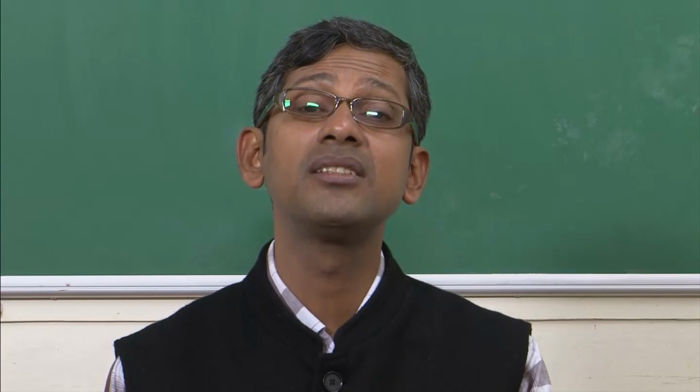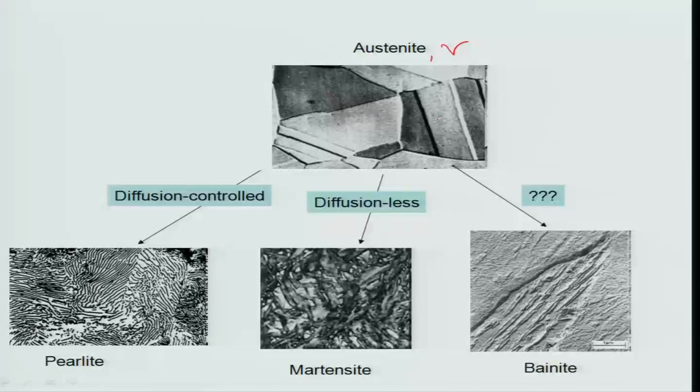Martensite is a single phase structure, unlike pearlite, consisting of needles of martensite. You can see here that the same structure can be bypassed by quenching or cooling rapidly, and we can obtain a different kind of structure called martensite. Martensite was an accidental discovery, which we will discuss in detail when we talk about it. It was discovered by Martens in Germany long back, accidentally.